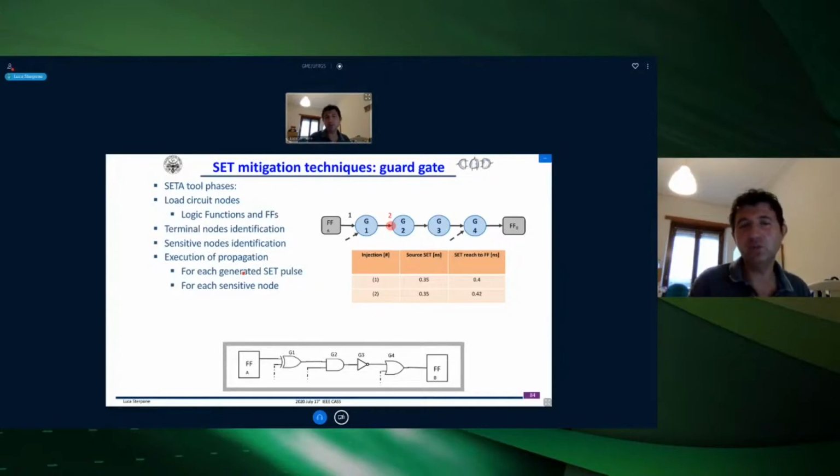The shielding can be too heavy for the satellite, and that needs to be smaller. On the other side, you can have particles with an energy that are crossing the shielding as well. And so, let's say, this is not possible to be addressed, okay? So you always need to use redundancy. Redundancy can be adopted with triple modular redundancy or even more. You can have NMR, so N-modular redundancy, in order to protect them. I think I can give you some feedback later on this phase.